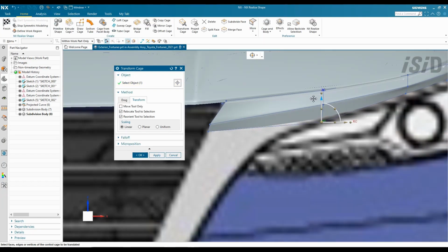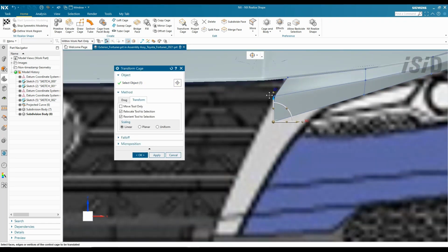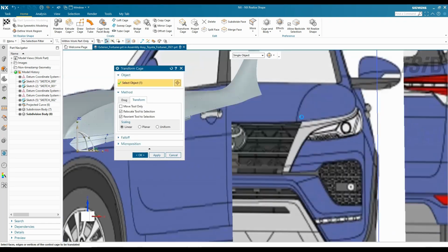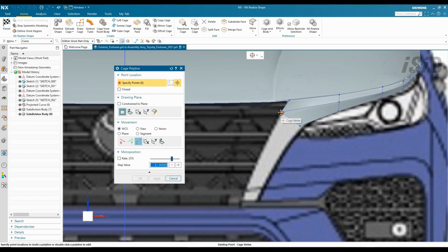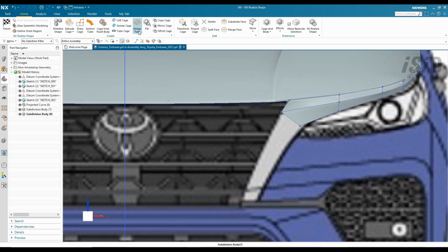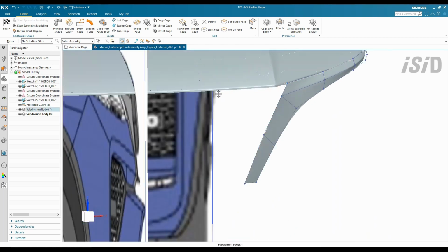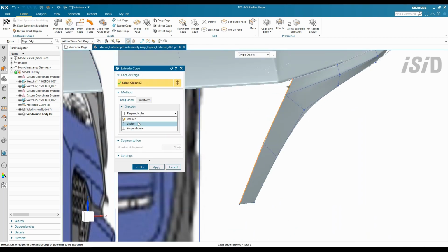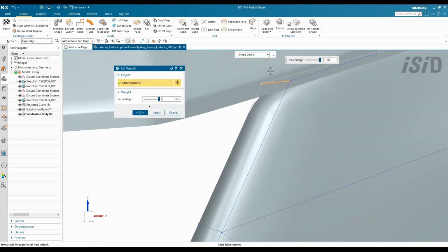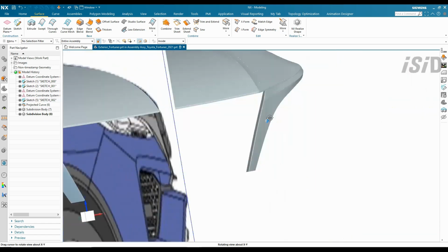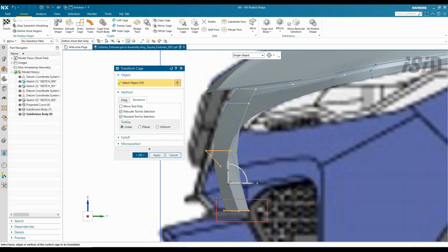So the workflow is almost the same for every single surface creation for this model. Again, I use this cage polyline and then sweep it. And I continue to refine the shape following the raster image.